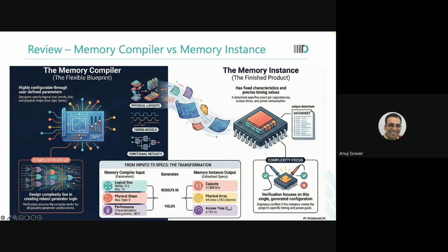Did you do DRC at the core level? Because this is GDS. So then you did DRC at a much later level. And once that was also done, you must have done a sign off, some timing driven sign off, and you would have said, okay, now tape out. Something like this happened.